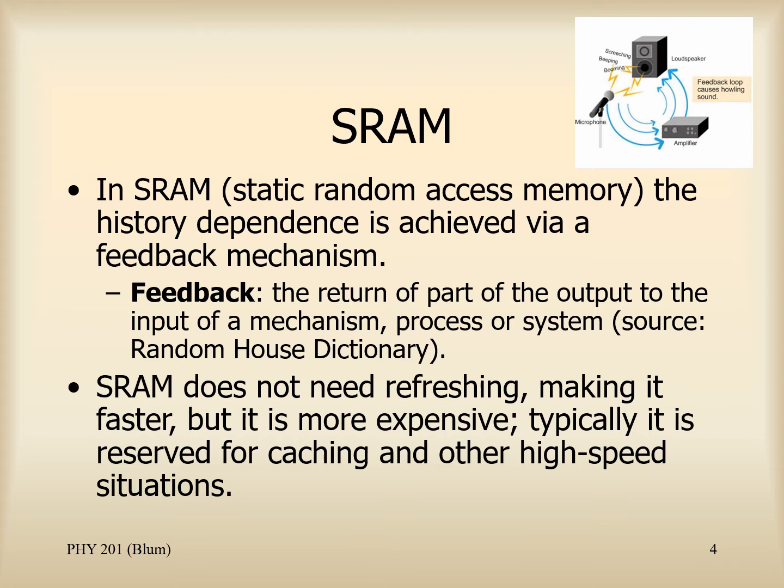And that means it's not going to require any refreshing. That's part of the reason it will be faster, but it's also going to be a more complicated circuit. So it's going to be more expensive and take up more space on a chip, and so it's usually reserved for special cases like caching or when we really need high speed.